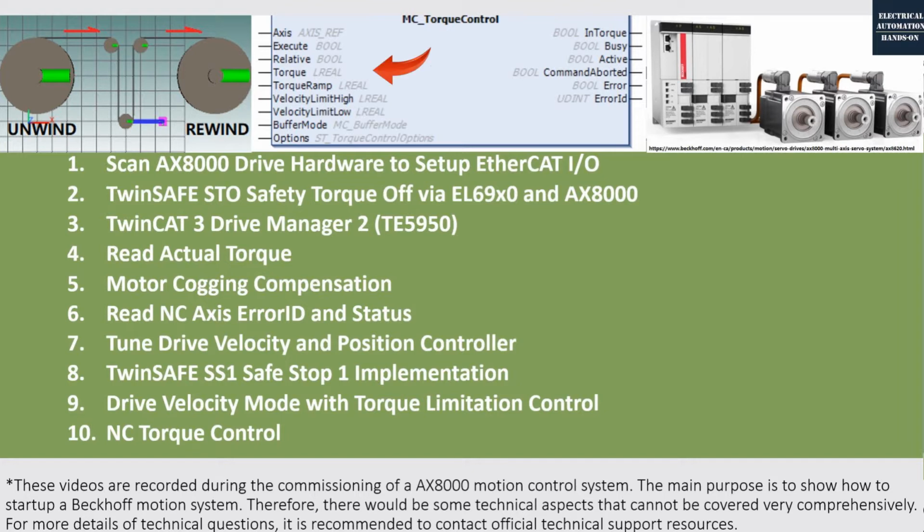In terms of the torque setting, basically the torque set point would come from your web tension. The web tension could come from your taper curve or some tension set point. So you can keep a certain torque on your drive and your web tension can be maintained by this drive torque. Maybe you will ask, why not use velocity control and a tension PID adjusting the velocity?